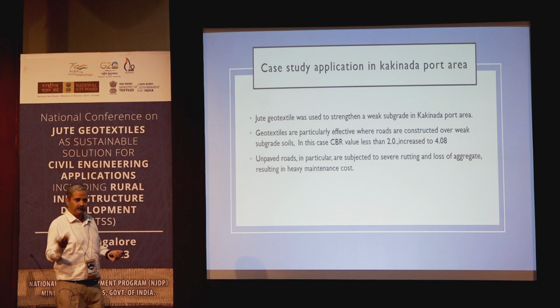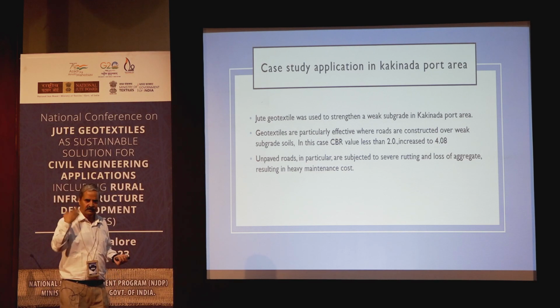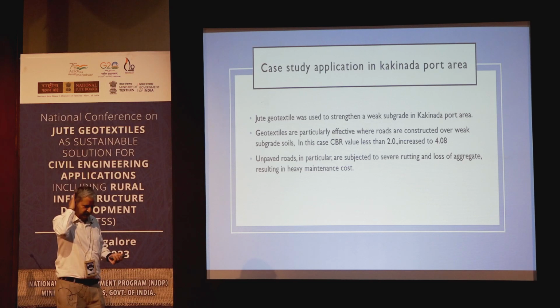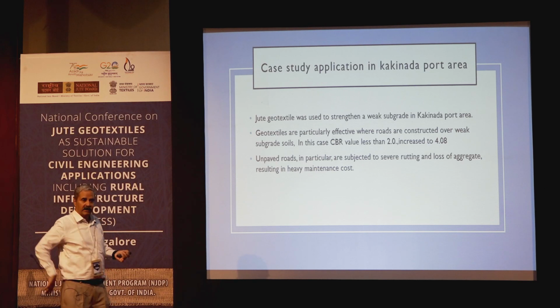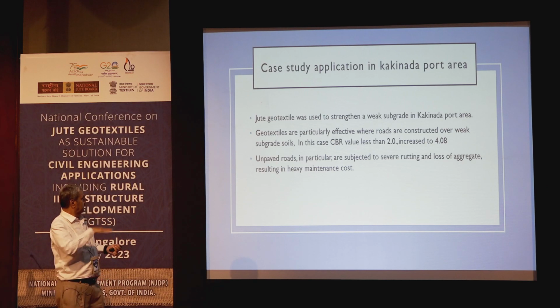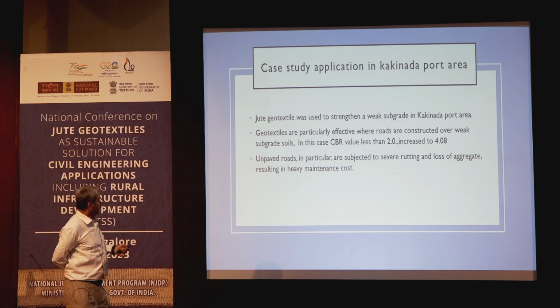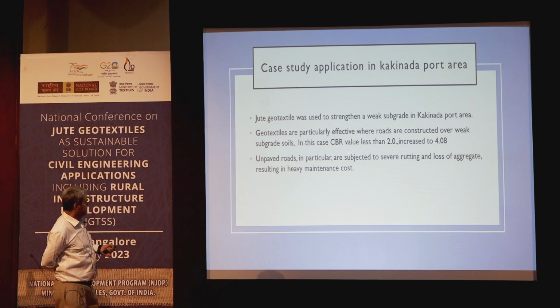I had two of my colleagues, Dr. Bindu Madhava. In fact, my friend Dr. Vasant is here. So we did three or four projects in Central Road Research Institute. One is on the embankment and soft soil. And the other thing I will just show. There, we wanted to improve the subgrade properties. Then the CBR value, when we showed, it was increased from 2 to 4.